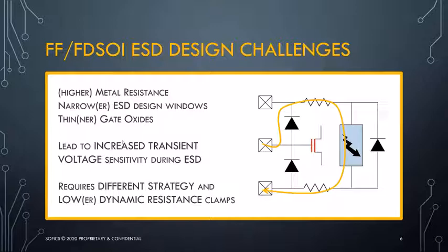On the right-hand side, we see a typical schematic of what we call dual diode ESD protection. It's very popular. Basically, it uses a diode to divert the stress from the signal line up or from the signal line down to the supply lines. And further, it relies on a power clamp which is dedicated between the upper and the lower supply line.